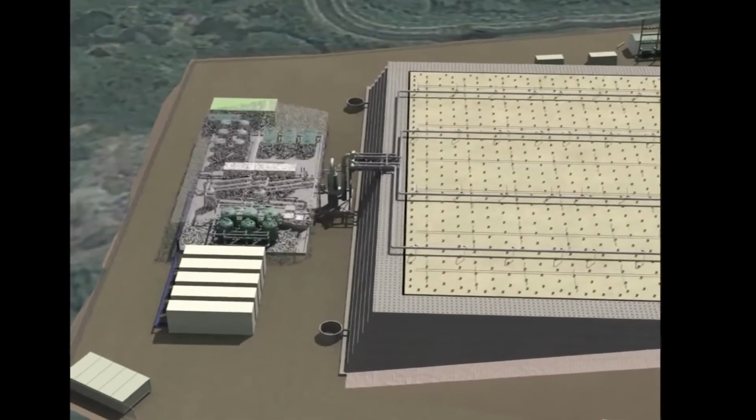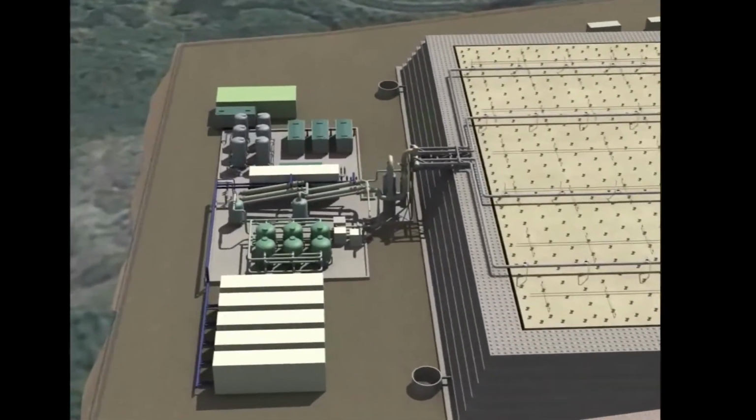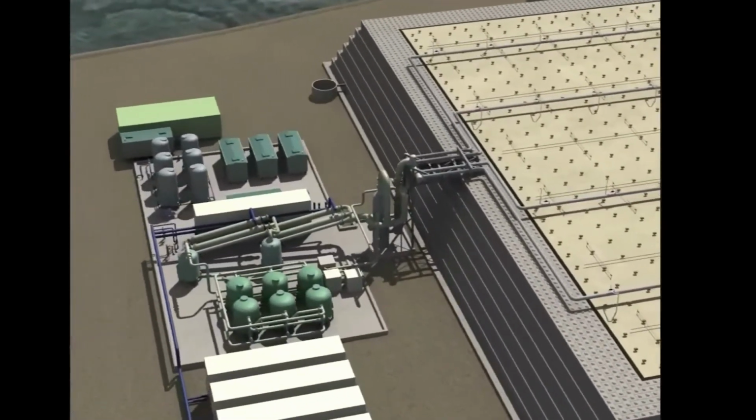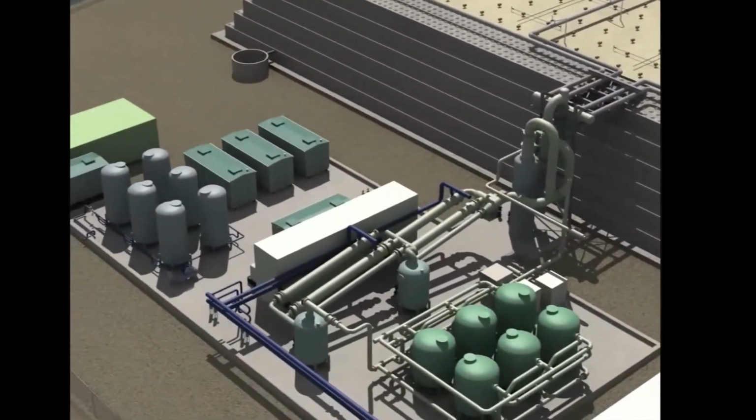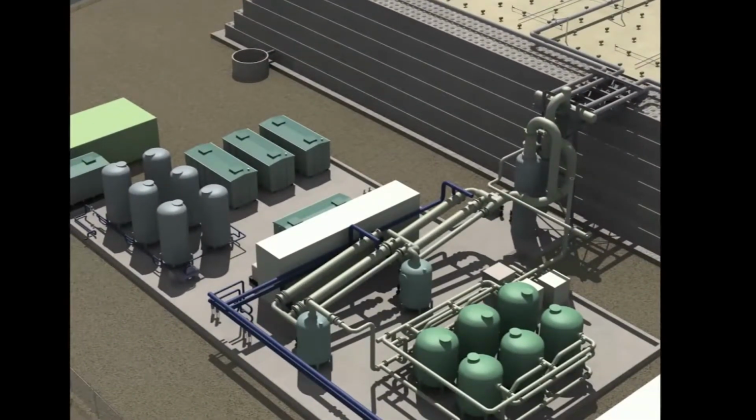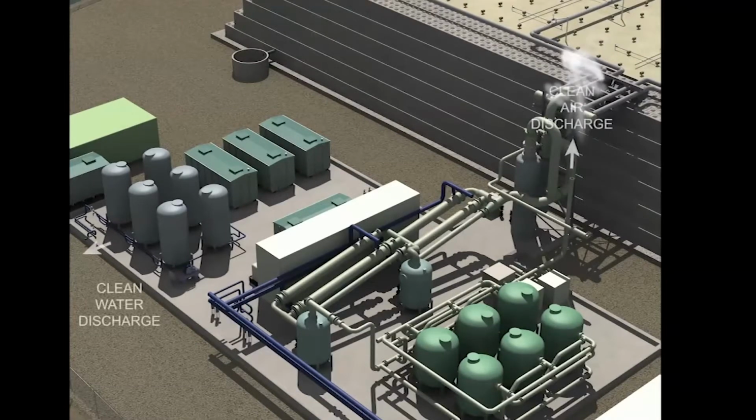Based on treatability studies and previous applications, approximately 95% of dioxin trapped in the soil and sediment at the Da Nang Airport is expected to be destroyed in the pile. The remaining dioxin will be collected as liquid and vapor waste and treated and tested in the respective water and vapor treatment systems before being released into the environment as clean water and clean air stream.